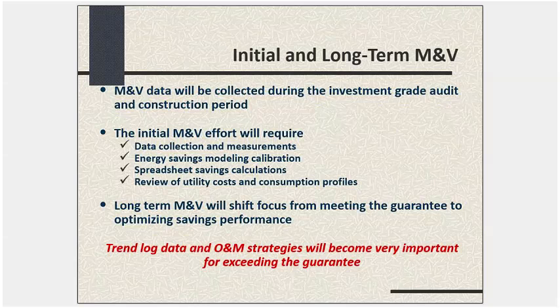The reason why is because the accuracy of these measurements has a pretty strong effect on the ability to evaluate savings in the future, because if you don't establish a correct baseline or standard of comparison, you won't be able to effectively measure the changes in key variables over time that are actually what defines the savings and the utility costs that you're going to avoid.